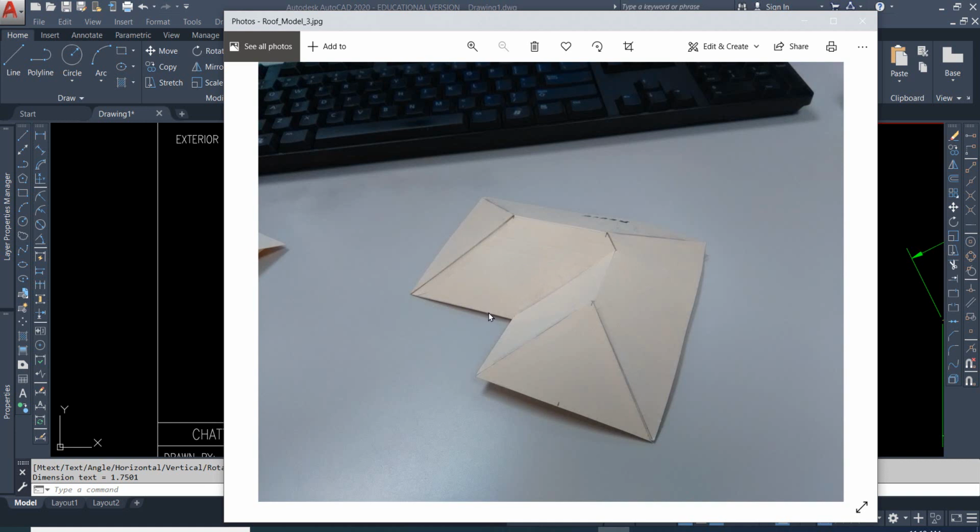The slope distance from an eave to the ridge is the same as from the eave here to the point. The width of it across here, the eave of the roof, will be the same distance measured off of the sketch. And you just find the midpoint of it and draw a perpendicular line, whatever the slope distance is, and then connect those two points to create an isosceles triangle. That gives you this end piece.